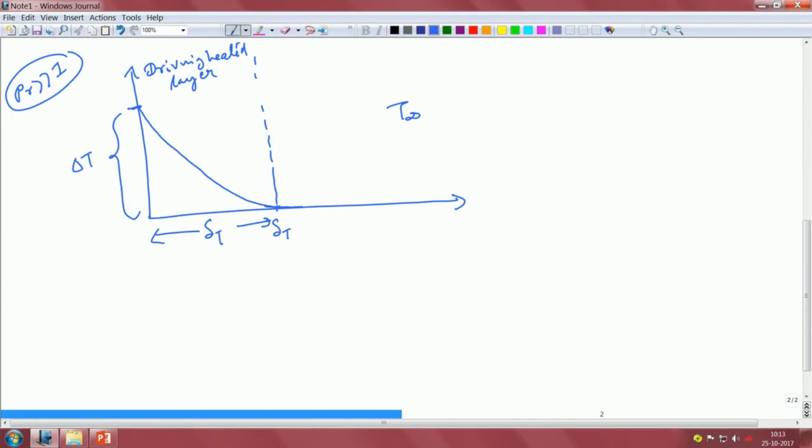That is standard boundary layer knowledge. So the driver for this problem is essentially this heated layer, whatever gas is getting heated around the wall is the driving mechanism for this buoyancy. And since it is a Prandtl number much greater than 1 problem, here you have a balance between friction and buoyancy. That is the nature.